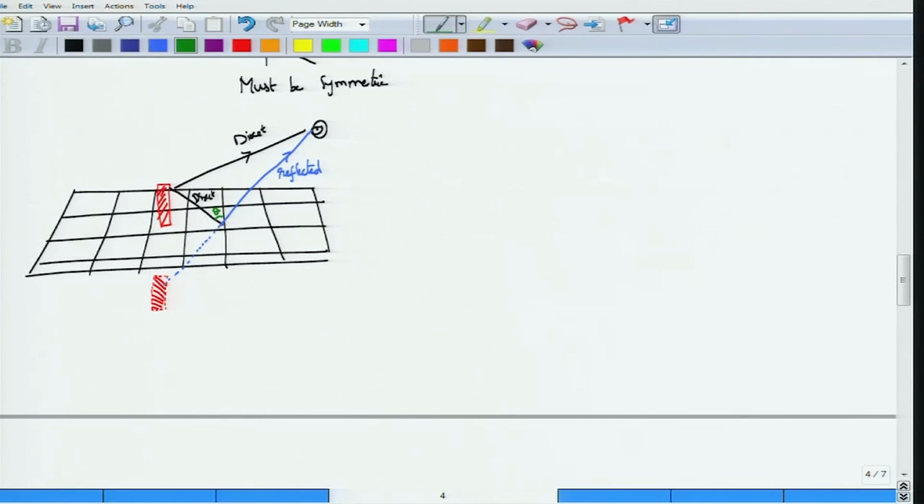The point here is that if you have a ground plane anywhere near the antenna, then the field pattern and the power pattern of the antenna gets modified. Sometimes you might use this concept of having a ground to your advantage. We will see one example when we discuss half wave dipole.